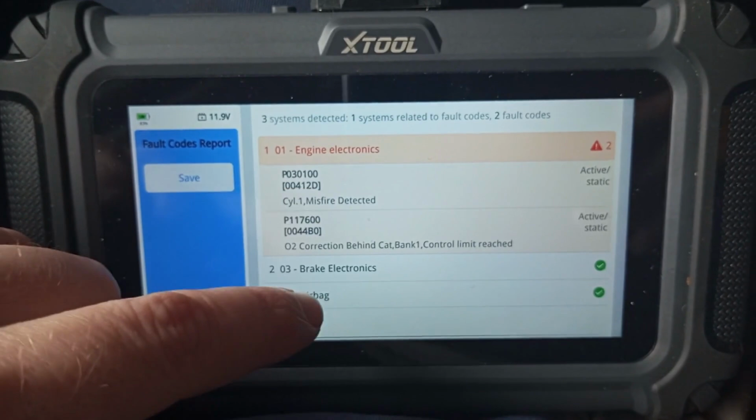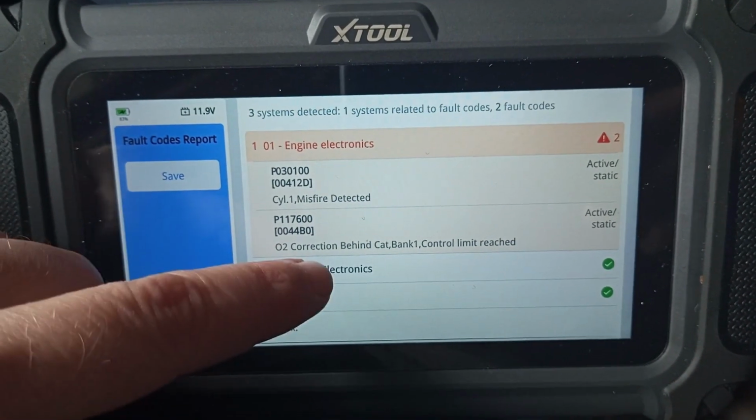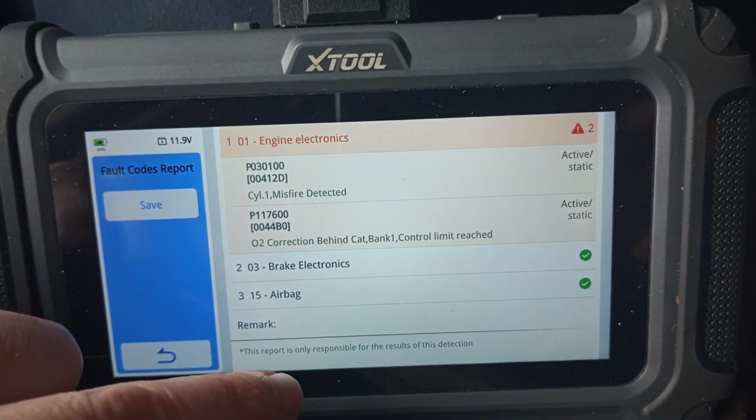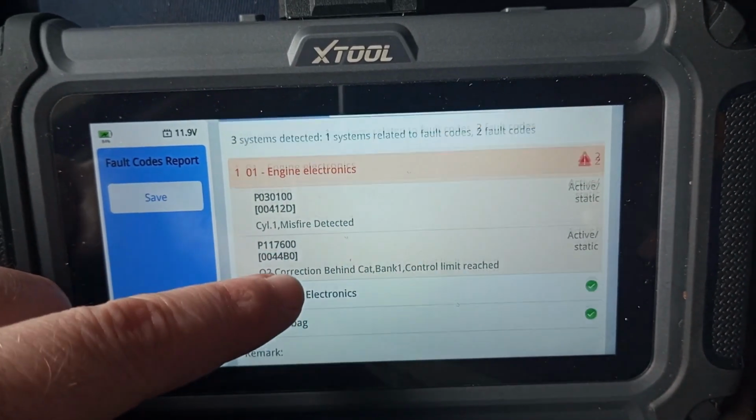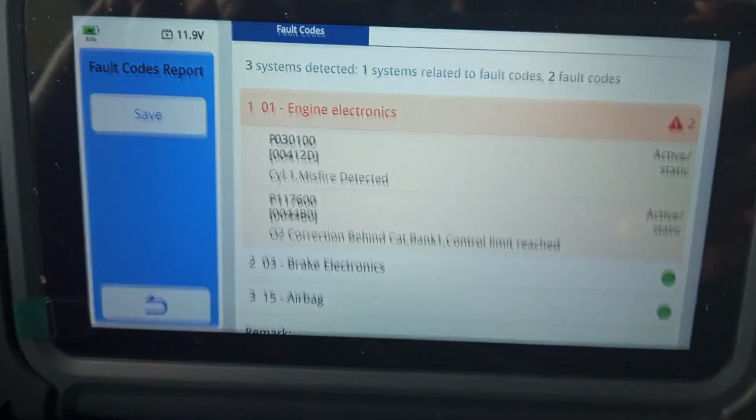What will the OBD tool enable you to do? Well, you connect it to the OBD port, and when reading the code, you'll get a definition of what's wrong. That tool will enable you to, if not exactly pinpoint the exact problem and the exact part that's causing the problem, at least pinpoint the system that is causing the problem, okay? So you don't have to wander around if it's the fuel system, the air intake system, the ignition system, and so on. The OBD system has its flaws also, it's not always 100% correct, but in the majority of cases, it's a big help and it will let you make a quick and correct diagnosis of the problem.